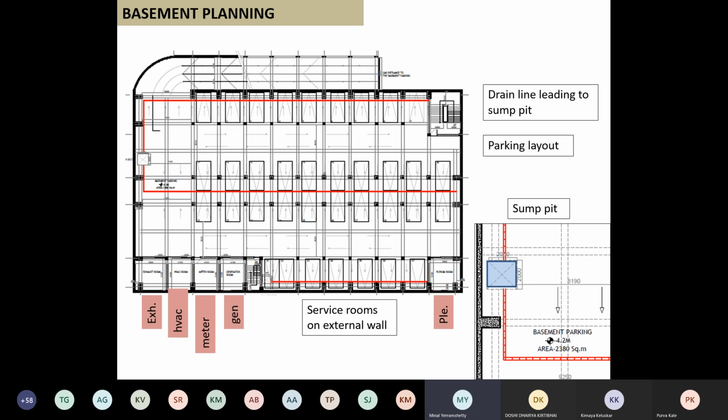See, the job of exhaust and plenum is that it does the mechanical ventilation for that entire area. But what about the ventilation for those rooms? There might be some pumps there. The fan could create some kind of heating up. So who will ventilate that? So I need to have a separate ventilation for that system as well. If you are going to give me that, go ahead, place it anywhere. I have no issues. Got it?